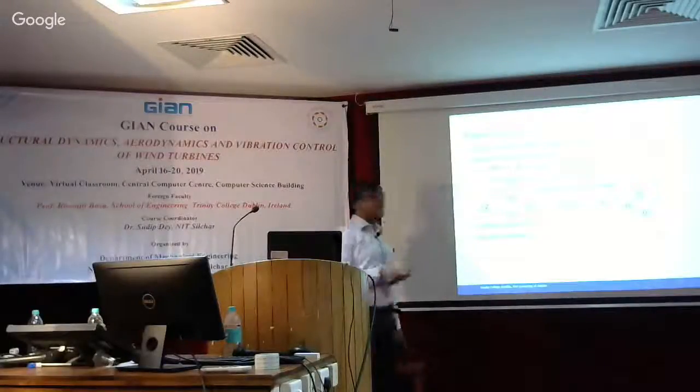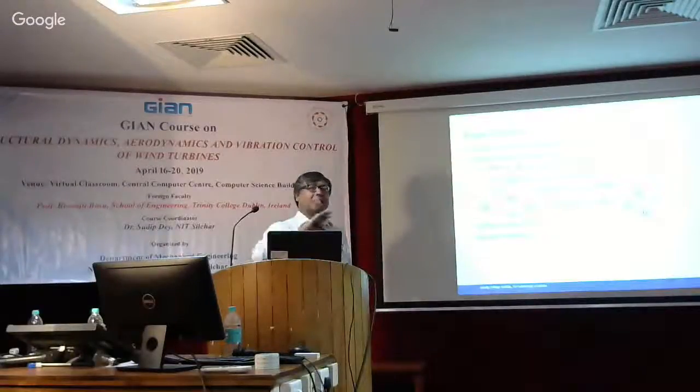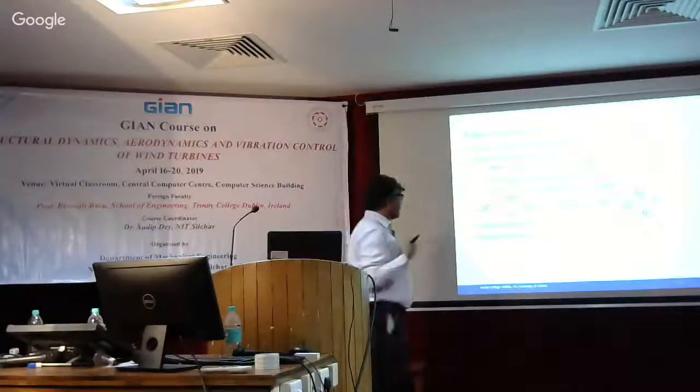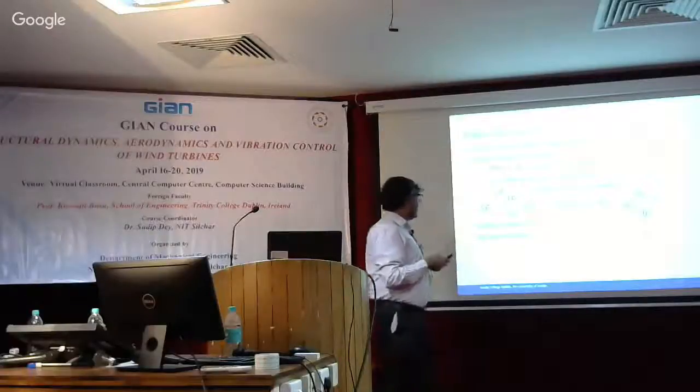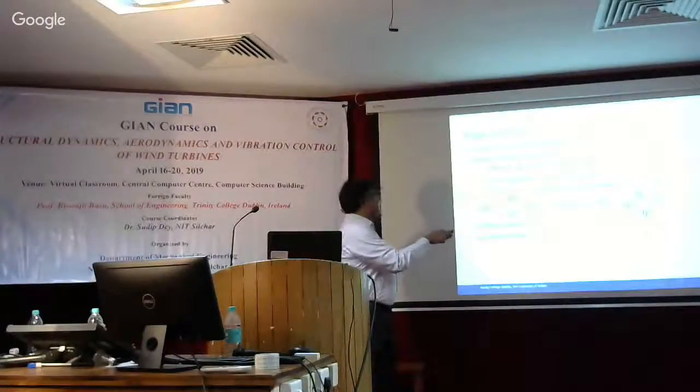And this is exactly what was done using the pitch control to provide additional damping to the tower. So that's very interesting now. You're controlling the tower of the wind turbine completely by using the pitch control of the blade, and that too by changing the aerodynamic load, in a way that introduces additional damping. Now, to do this, the only thing you have to make sure is that you need to know what this delta F is going to be.